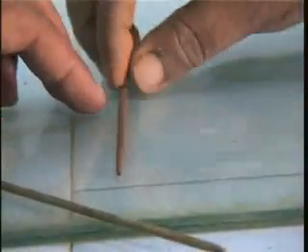And you can see that this could be rolled to 3 millimeter size, and the sample didn't crack. So we need to have a little bit drier sample, and if it is slightly drier than that one, then we won't be able to roll a thread of 3 millimeter size. You will see that in the next little bit.